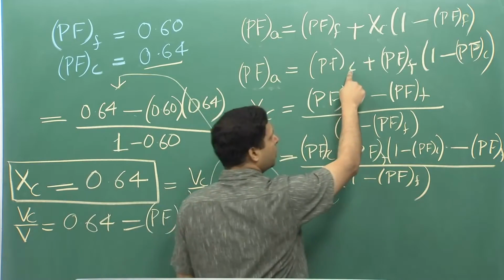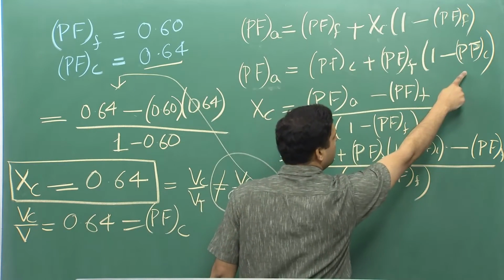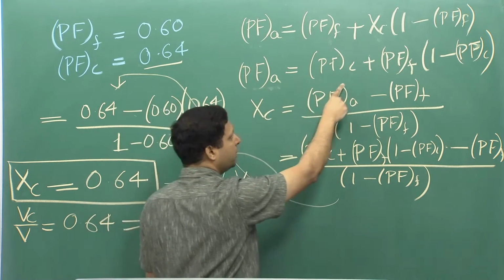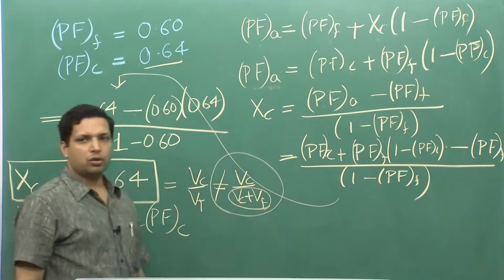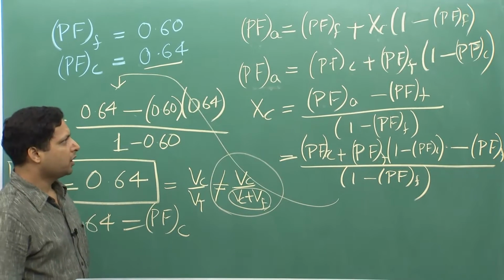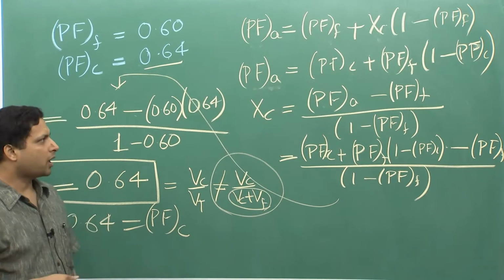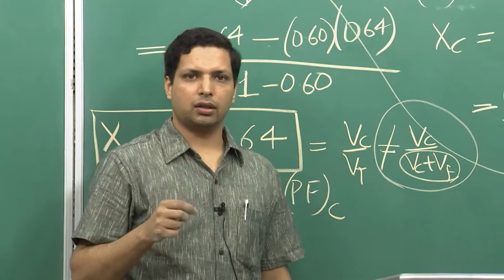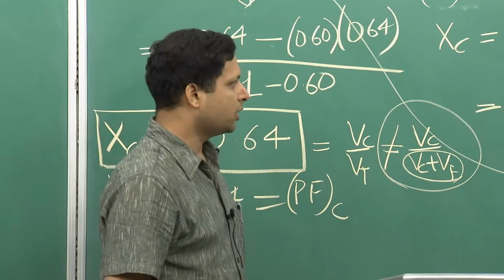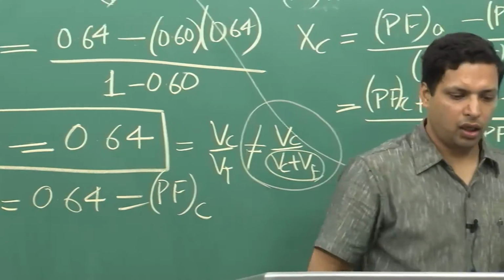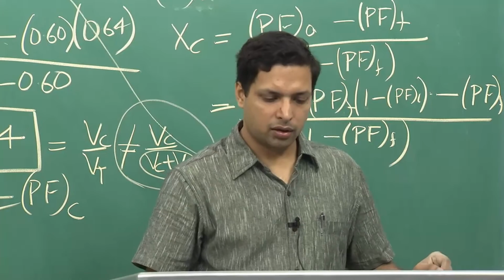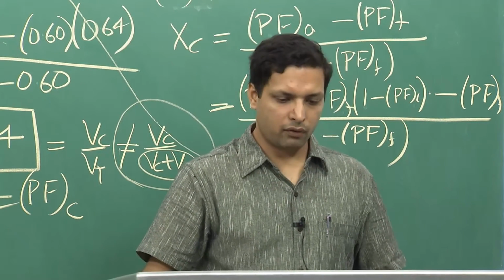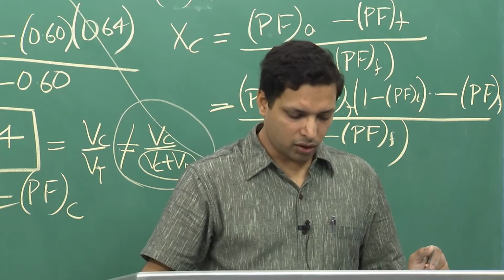Now you know the coarse, the fine, and all the parameters over here. So, you can put those over here and you would see that it will come to close to 0.74 something when you put those numbers. So, again you are increasing the packing fraction when you have the bimodal grain size distribution. With that we come to the end of this subtopic, which was the consolidation, and we will move on to our next topic, which is compaction.